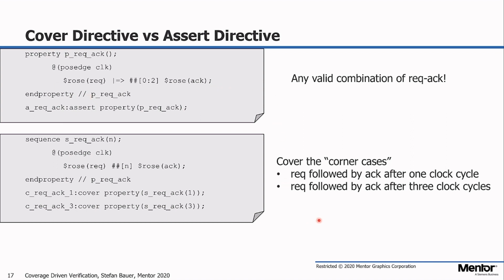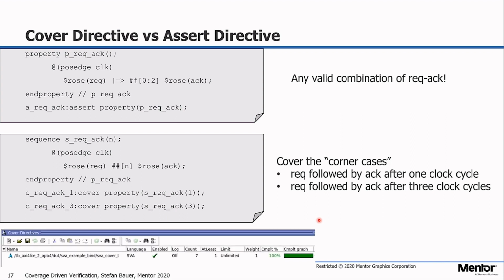And that's the difference. So in ModelSim and Questa, we provide you a cover directive window where you can view and analyze the status of your current cover directives. That means we will add these 2 items you will see in the cover directives item, and in the end you will see if you have fully covered it or not.